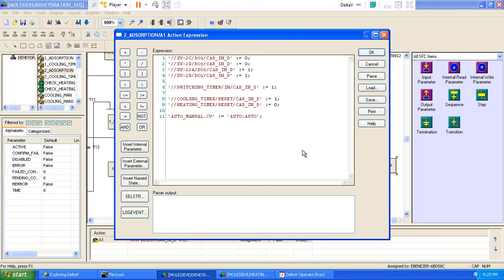Because we have, what are they called? Cold boxes made up of aluminum, and you don't want hot gases to actually damage those units. So we may just do extra connections, comparisons, or checks at the transition level to see whether the temperature is okay and within range. All right, but we don't have that at this point.